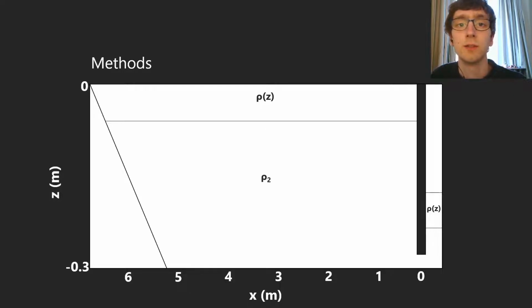of fluid added to the top, which has the same density as the fluid at the surface of the main tank. This causes the pycnocline to be displaced behind the gate, so that when the gate is removed or the simulation is started, an internal oscillatory wave propagates from right to left. On the far side of the tank is the slope, which we vary in steepness, and where necessary we can extend the length of the numerical tank to extend our slope steepnesses.